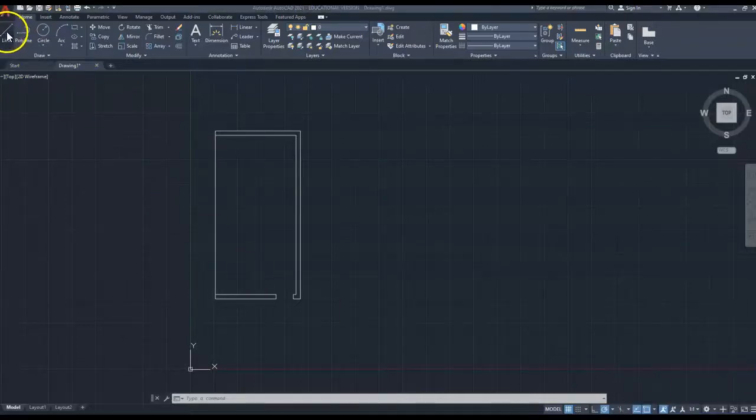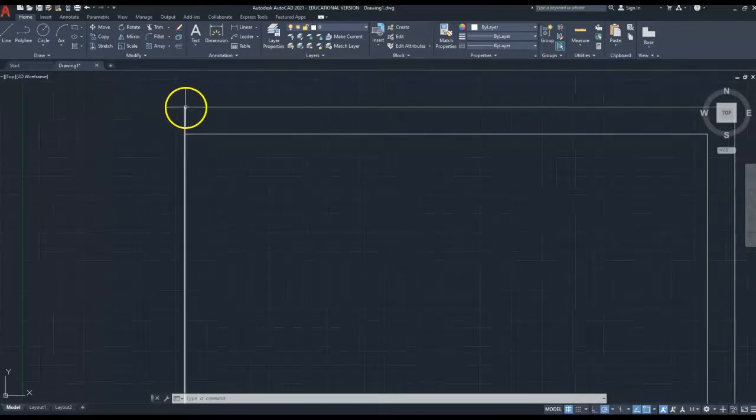Anyway, so I'm going to click the line function again. And once again, I'm going to zoom in because my eyes aren't what they used to be. Zoom in a little bit. So select the line function. When that little green square comes, that means it's locked onto the end of the building, which is great. That's what I want. So now I can pull across here. And again, I'm just going to go 150 mil.